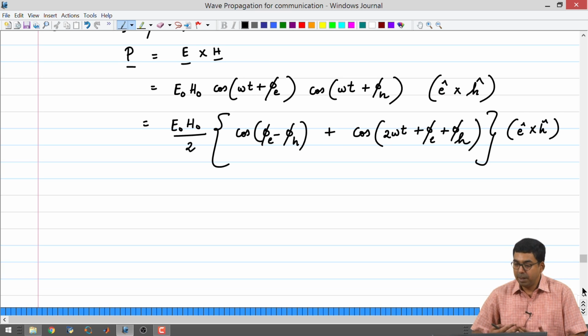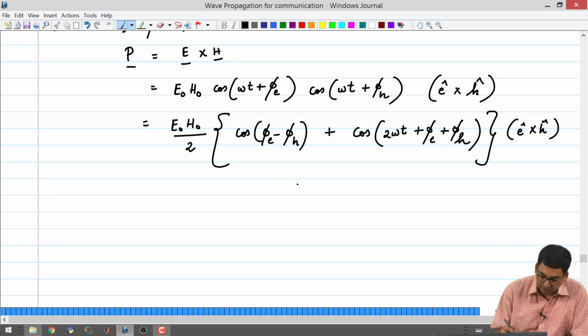Same way you can have instantaneous power to be positive, which is fine for you to draw some conclusions normally, but at some other instance of time you will have negative. So, this is not an easy quantity to interpret to make physical inferences. It is not the best quantity for making physical inferences, because it can be positive, negative or 0.